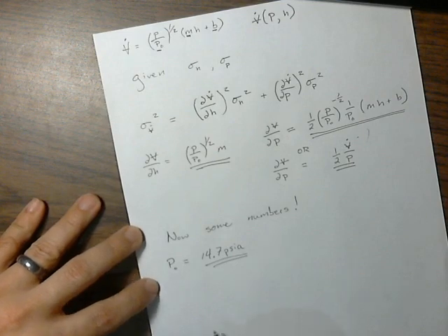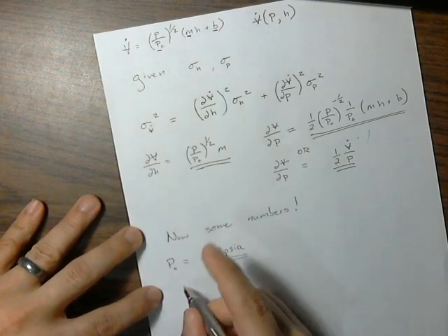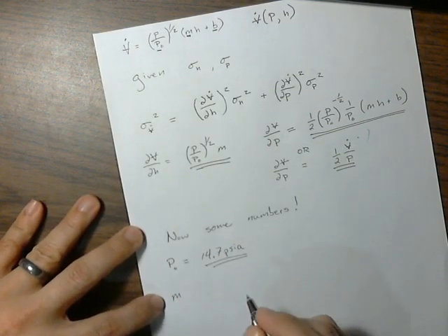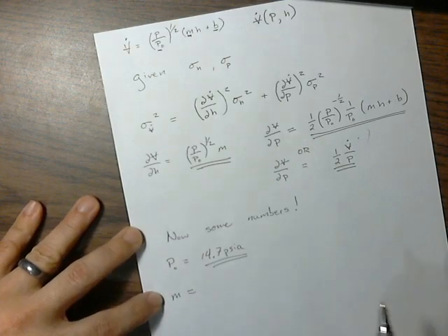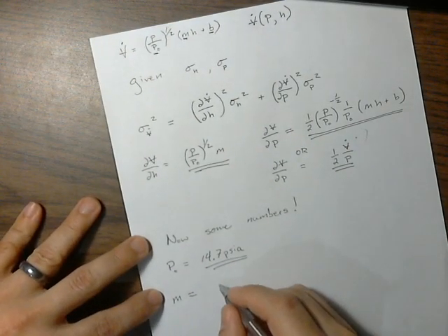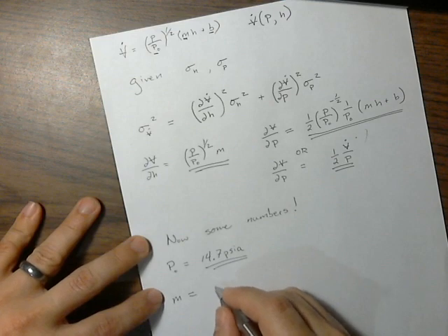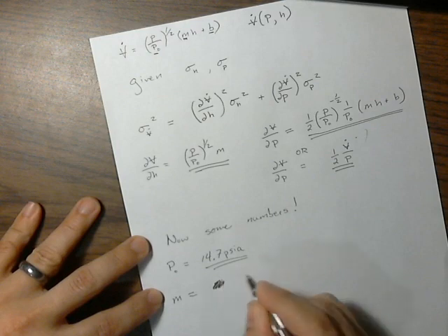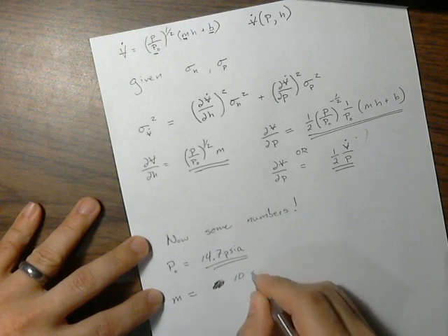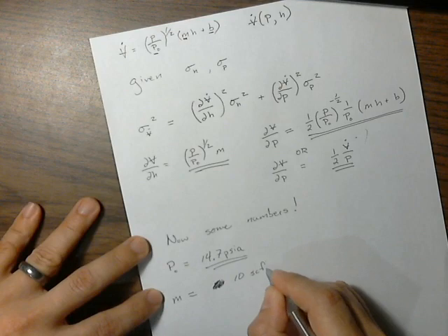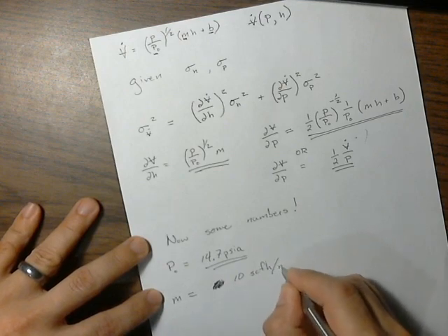So we needed that. For my slope M, let's say we're working in crazy English units, which are common in the welding industry. We'll say that M is, I don't know, 20, no, that's pretty high. We'll cut that in half. We'll say 10 SCFH per millimeter.